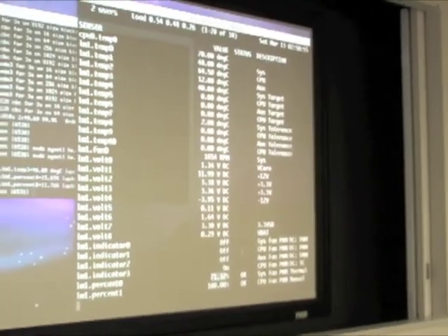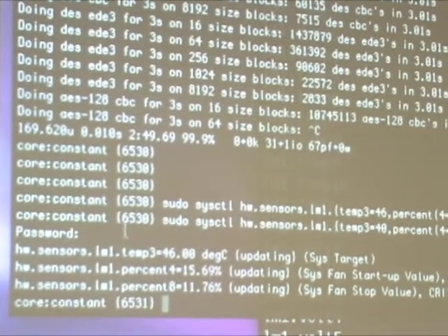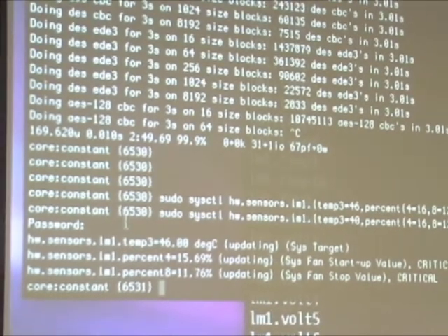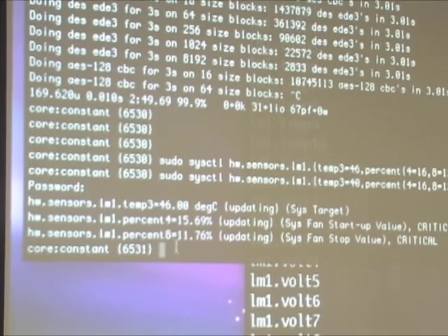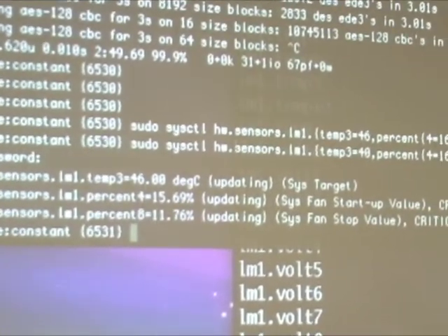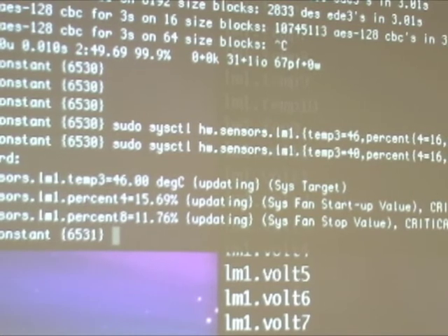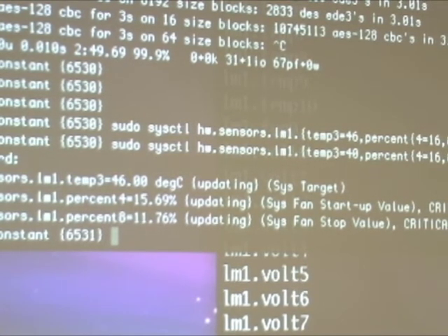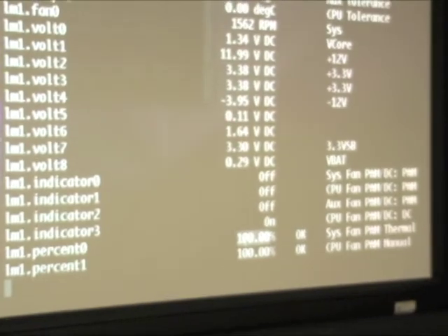So I'm not changing anything. When I write this command, what happens is these values get passed to the data structures that the driver is going to look at. Then the driver, in a single refresh procedure, writes these new values that I supply on the command line to the chip. After that, the driver simply reads the values back from the chip. Because the value was changing slowly over time, it means that the chip itself automatically changes its value slowly over time.